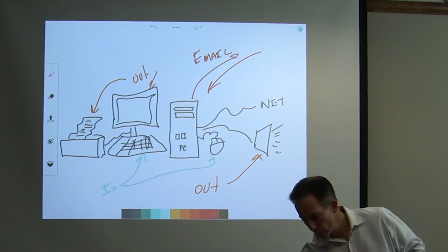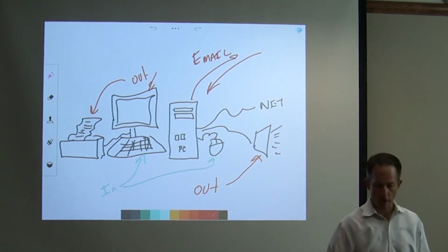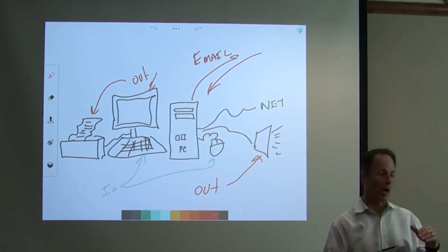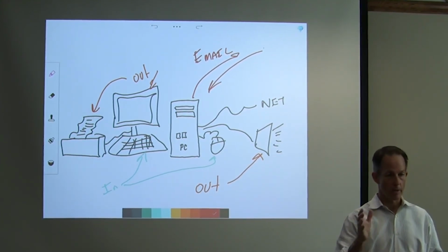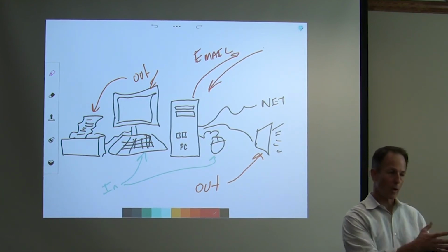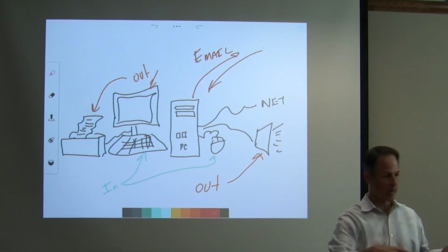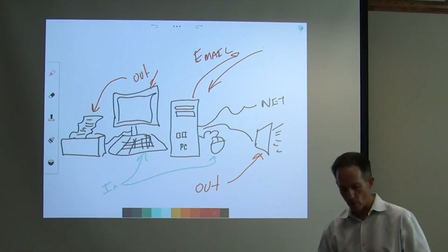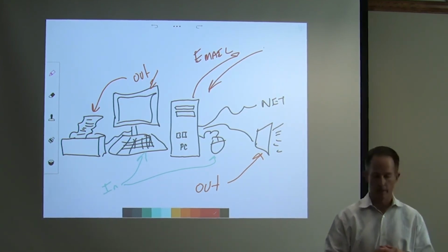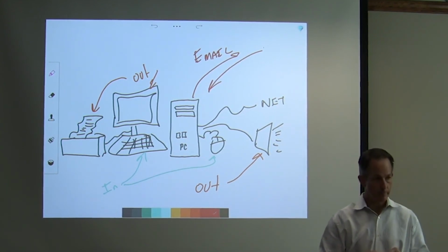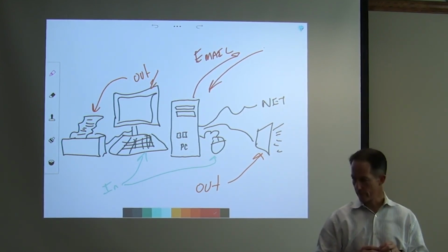Usually a bright yellow means that we have lost communication. That could be the comm line is down, the network is down, or it could be power is down. It could be localized to one transformer taken out, four or five of them, or just one controller that bit the farm for some reason. So more yellow if communications is down, and orange is the power's out?